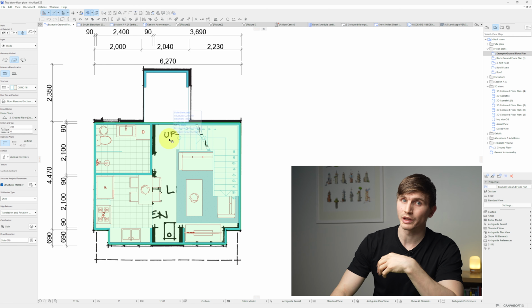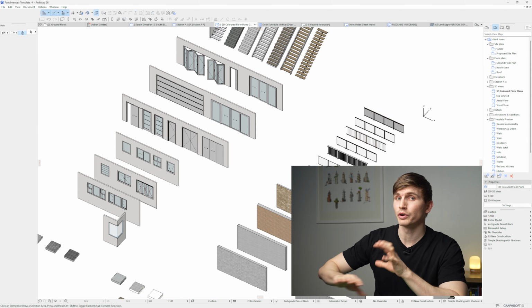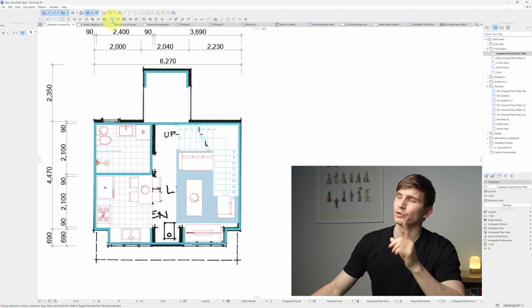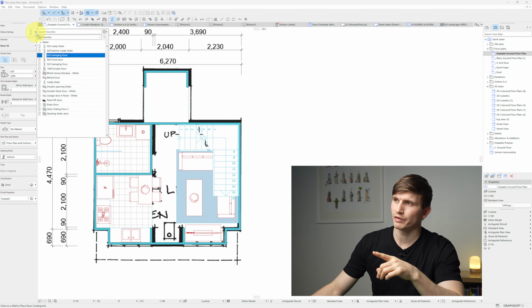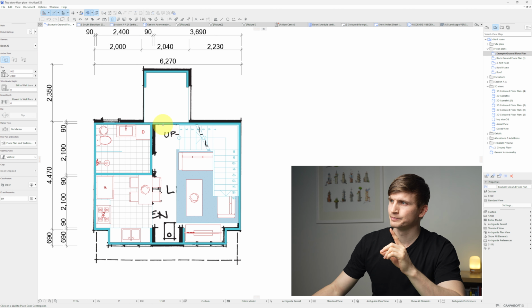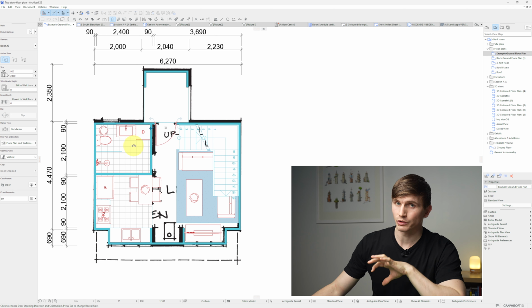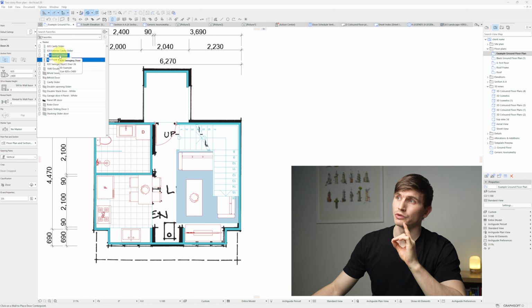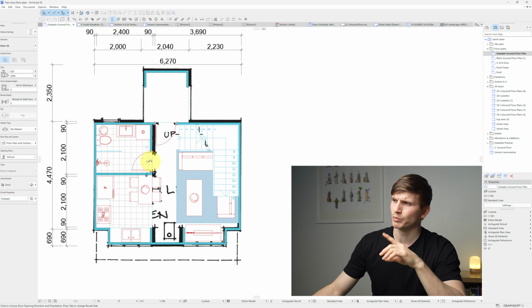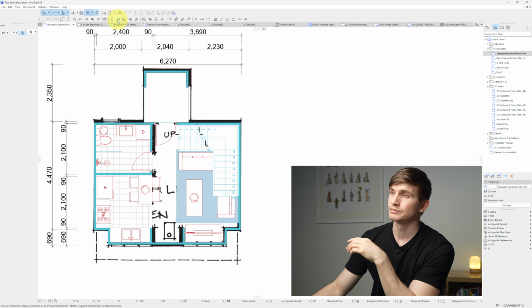Finally, this leaves us with our walls and windows. In the template, we've already got a bunch preset and ready to go. So if we just go to our door tool, we'll go to our favorites, and let's select our front door. Nice big 920, we'll bring that one so it's facing inside. And for the remaining doors, we'll go to an 820 swinging door, and we'll place that one just into the bathroom.